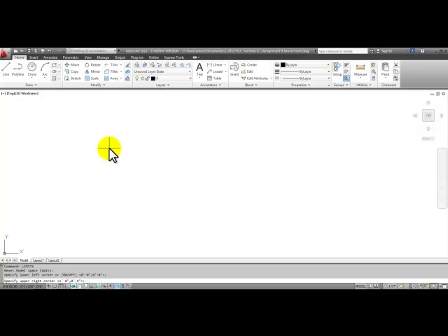And then the upper right corner, which is establishing a lower left and upper right corner for our workspace, is by default only 1 foot over and 9 inches up. Because our floor plan is about 25 feet by 25 feet, we're going to type in 25 feet using the apostrophe that's just to the left of the enter key, 25 feet, comma, 25 feet, and then press enter.